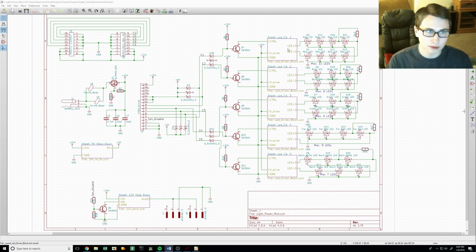This will be used for PWM control to change the brightness of each LED channel from 0 to 100% of its maximum value. We'll talk about the Schottky diodes and input power filter in a future video and why this was required, since it wasn't in the original design.